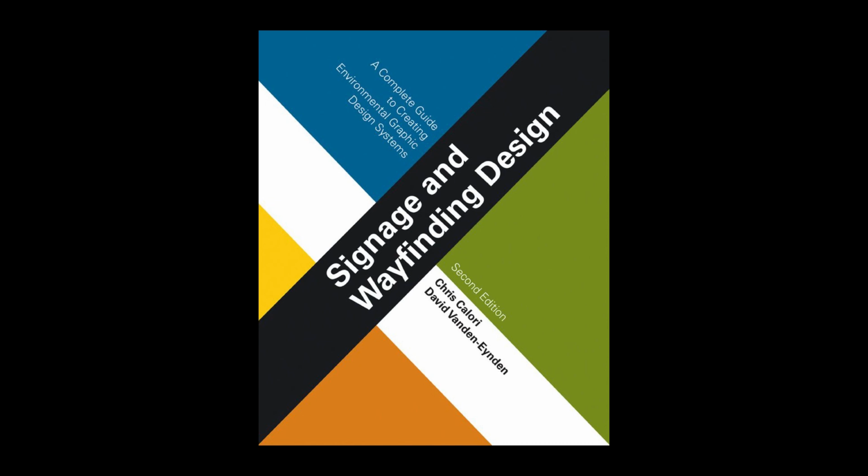Dimensioning and scale. Size is another essential piece of information that needs to be conveyed about each unit in a sign program, so all design drawings must be dimensioned. The extent of dimensioning depends on the complexity of a given sign type, but at the very least, overall dimensions, height, width, and depth, should be indicated, as well as the dimensions of any components of the sign type. For example, the overall dimensions of a post and panel sign unit are indicated, along with the dimensions for the post component and for the panel component.